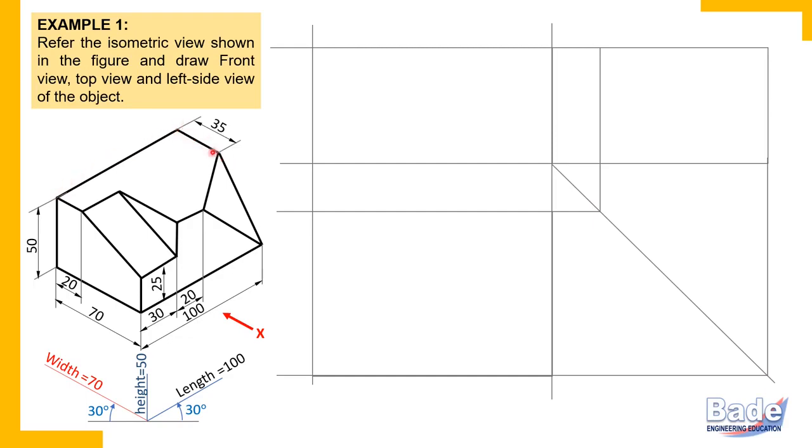Length axis and width axis are perpendicular to each other. That means this angle, even if it doesn't appear 90 degrees, we are sure that this angle is actually 90 degrees. You know that in a three-dimensional diagram, shapes get distorted, angles get distorted. So this angle is really 90 degrees. So this principal edge is parallel to length, this principal edge is parallel to width. So that means this surface has two perpendicular principal edges. So this is a principal surface.